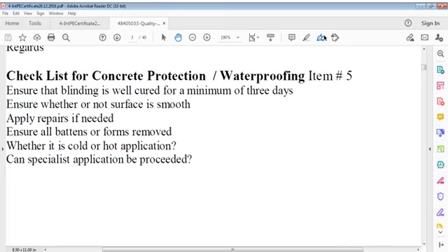So, for concrete protection purposes, your structural surface should not be adversely impacted by such impact of water and soil on foundation. For that purpose, we create one barrier on all surfaces in foundation, horizontal and vertical, above blinding, and wrap them completely.